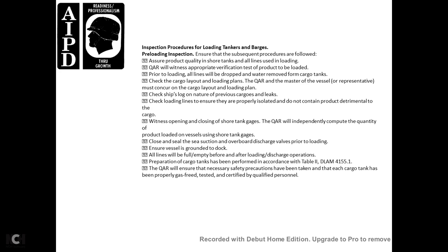Witness the opening and closing of the shore tanks. The QAR will independently compute the quantity of product loaded on the vessel using the shore tank gauges. Close and seal the suction, overboard and discharge valves prior to loading. Ensure the vessel is grounded to the dock. All lines will be empty before and after loading and discharge operations.